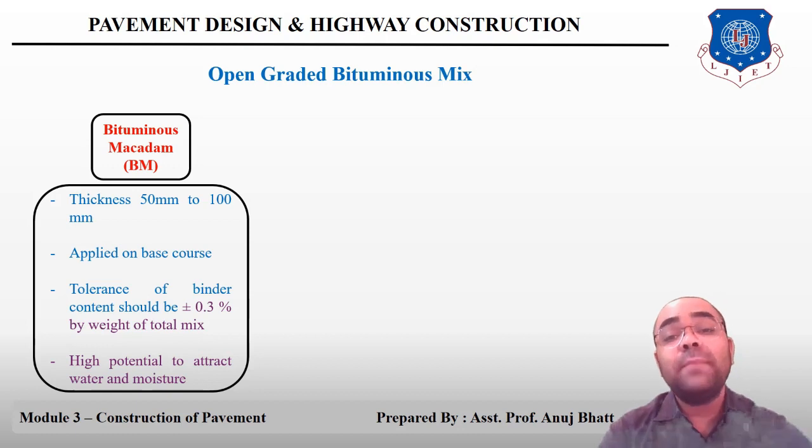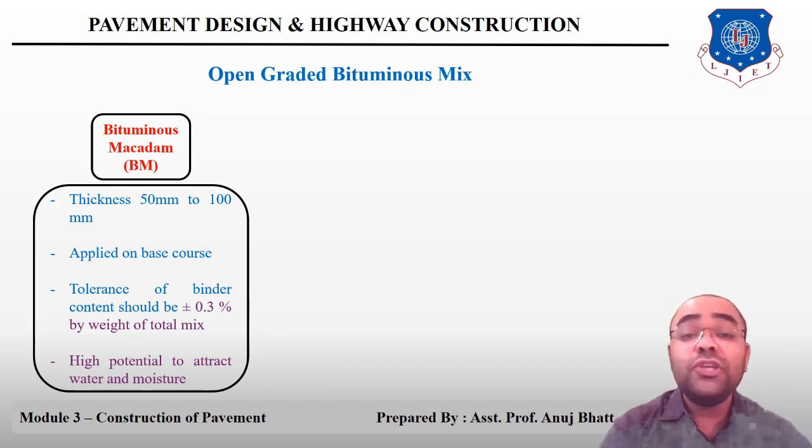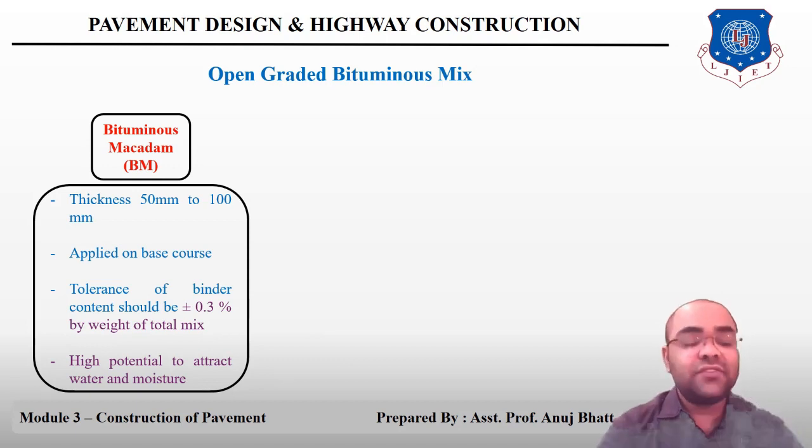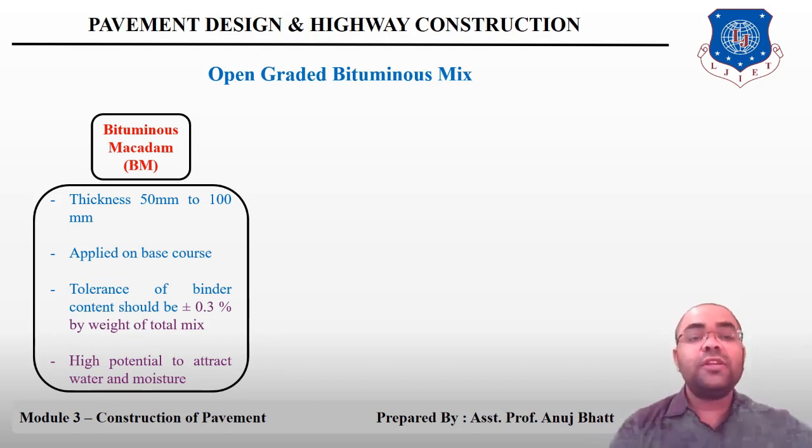In bituminous macadam mix, the bitumen to be used depends upon the climatic condition and the traffic amount. The natural sand shall not be used in the binder course. The binder content shall be within a tolerance of plus or minus 0.3% by weight of total mix. That is all about the bituminous macadam.